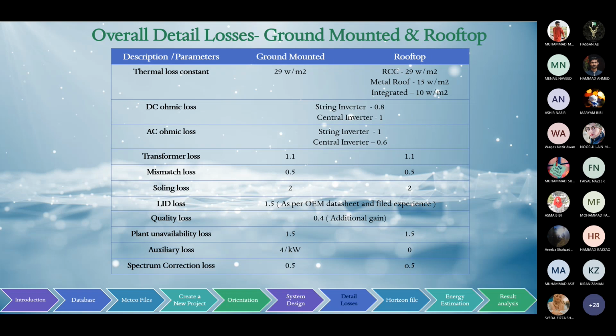2% means it's not a desert region. For normal land, slope terrain or any moderate slope terrain, in those regions we have to consider 2% of soiling losses. Soiling means what percentage of soiling is accumulated on the solar PV surface. So what is the cycle required for cleaning the module? Those factors we need to consider for the soiling factor of 2% in PVsyst.